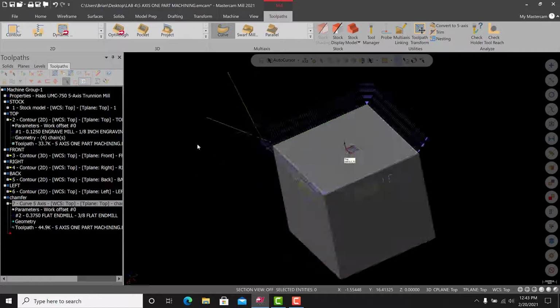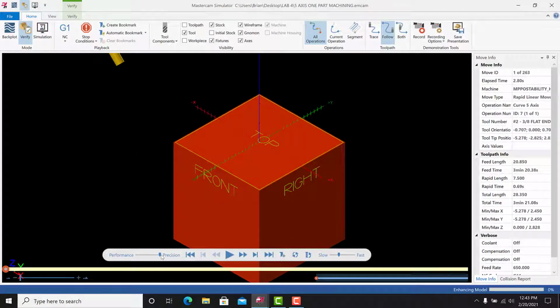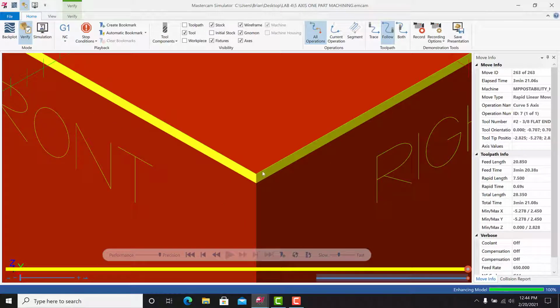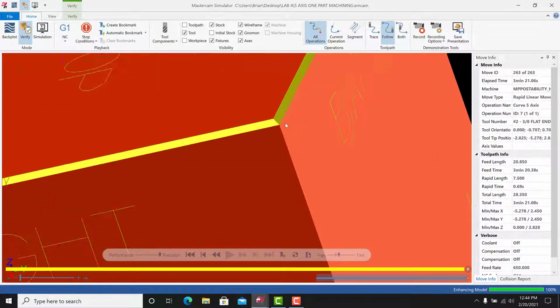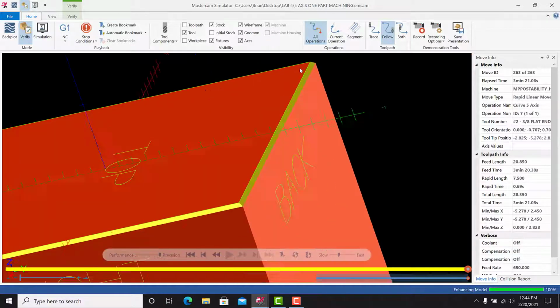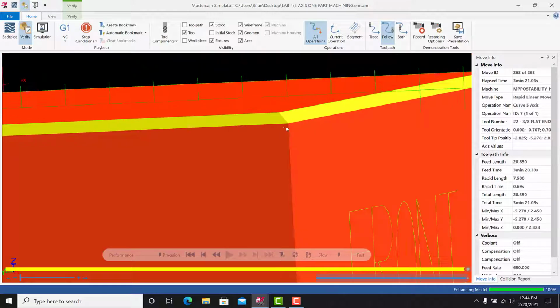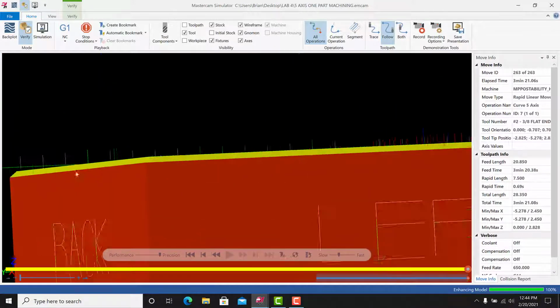Let's get an isometric here, and let's watch this and verify. And I have my precision way up to make sure I'm not getting any weird stuff on the corners, so we'll hit play. And it looks pretty good. Okay. And again, I guess there's no reason to do a chamfer like this. There's other ways to do a chamfer mill. This is just a real easy tool path. Just to show you some of the basics on this that go along with this simple part.